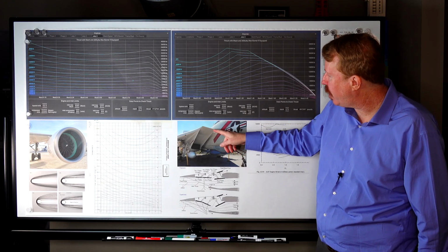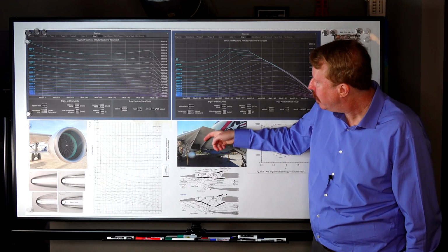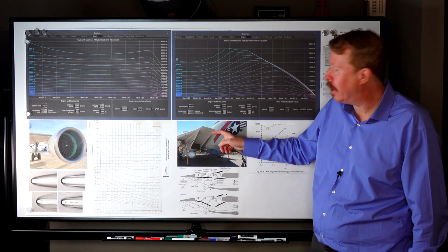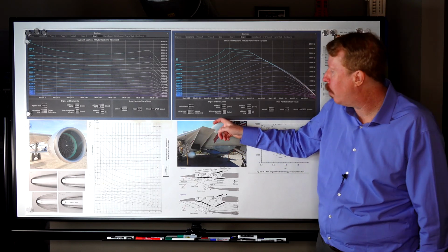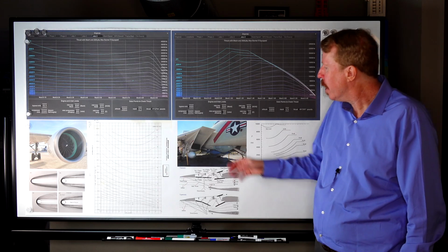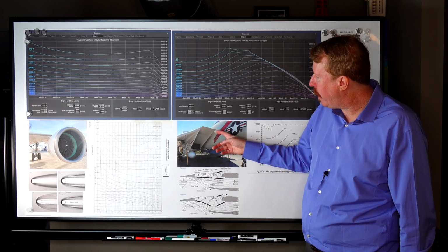And the oblique shock coming off of this lip here stays out of the engine inlet. That's why the inlet is swept back. Don't let the shock wave come back into the inlet. And so with this sharp leading edge here, the swept inlet, and then all the control they do for what air is allowed to go when and where at various different Mach numbers, they actually manage to preserve their ram air effect even above the speed of sound.